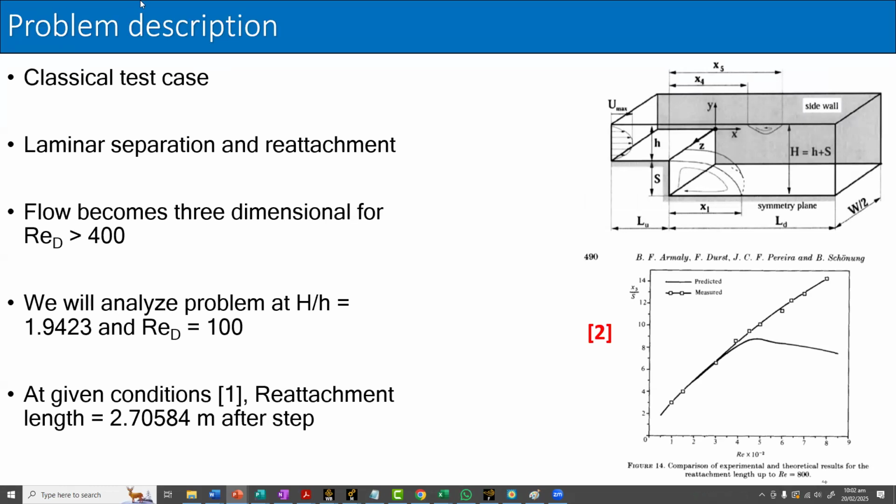Here you see that this part is the inlet, and one thing you can see is that they applied a velocity profile. You might ask, why a velocity profile? Because this is a parabolic velocity profile. In the case of, let's say, a simple pipe, it will take some time to establish the flow, which we call the fully developed flow. That is the entrance length.